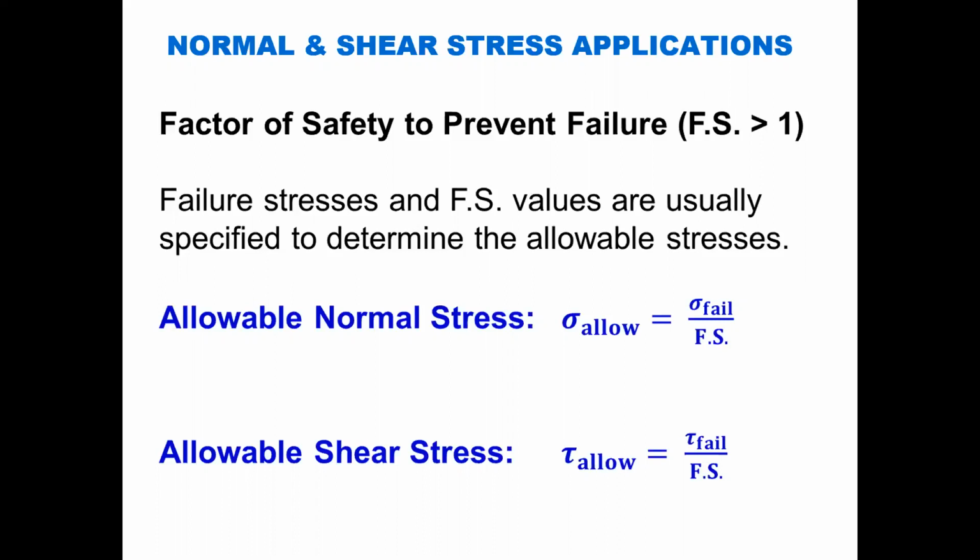Like I said, this is kind of a first generation of design philosophy, but it's a really good place to start because it's a nice, convenient, straightforward way to think about design. We have some sort of failure stress and we divide by a factor of safety greater than 1 to make sure that the actual stresses that we have in the structure are never larger than these allowable values.